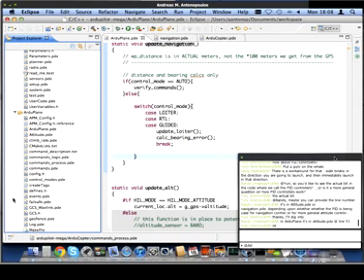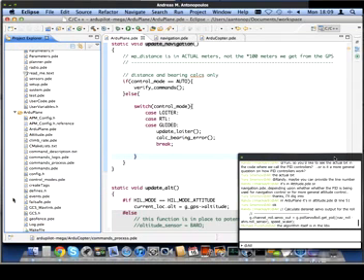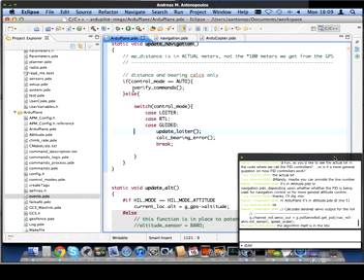So it then cuts the throttle and tries to glide in, and once it reaches that magic point of 3 meters vertically or 2 seconds horizontally before the landing point, it will also lock its heading. It will take the current compass bearing and try to hold that bearing, so it doesn't try to turn. That's important because if it tried to turn, that would roll the plane over, and your wing might touch the runway and your plane might flip over as the wing catches. So it tries to hold the plane as level as possible.